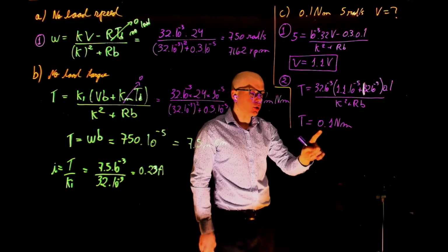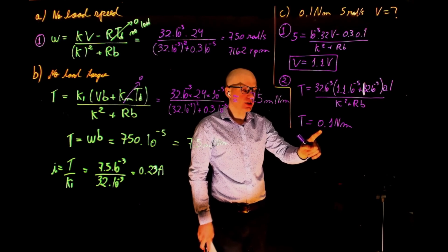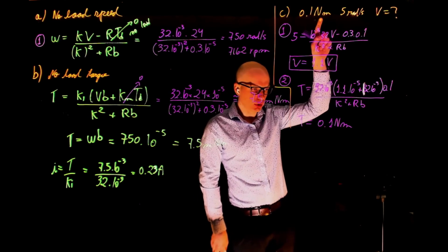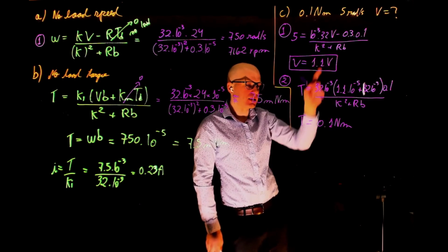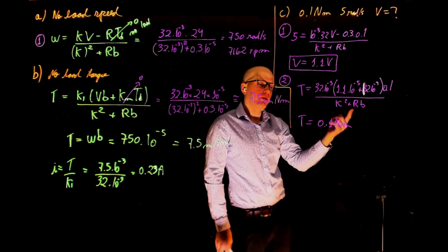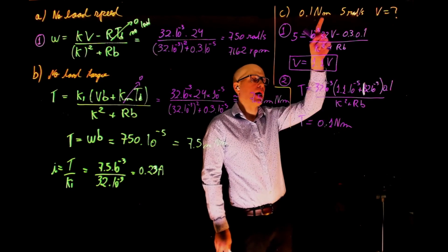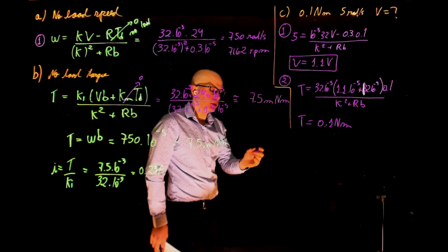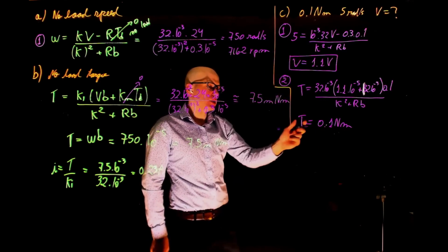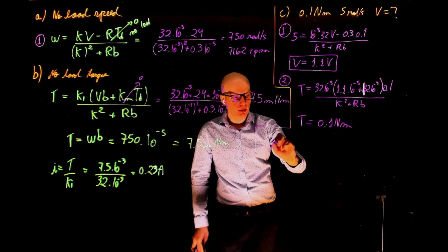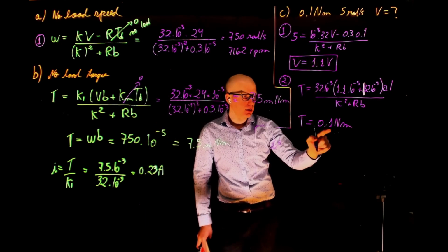All right, so this torque is the torque that includes the effect of friction. This torque here is the load torque. They happen to be the same because 10 to the power of -5 is negligible, but if it wasn't, then this torque would be higher than that. So which one should we take into account to calculate the current? The first or the second? Second. The second.